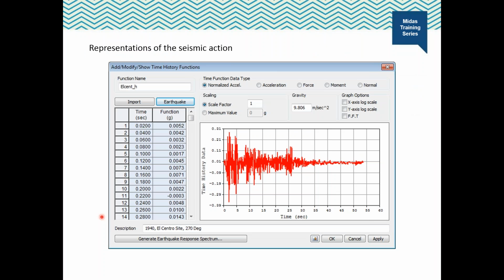The ground motion due to earthquake is measured in the form of acceleration. 3 accelerograms are recorded simultaneously along 3 mutually perpendicular directions to capture the complete oscillation of the ground at a location. The ground acceleration shown here is obtained from El Centro site in 1940.